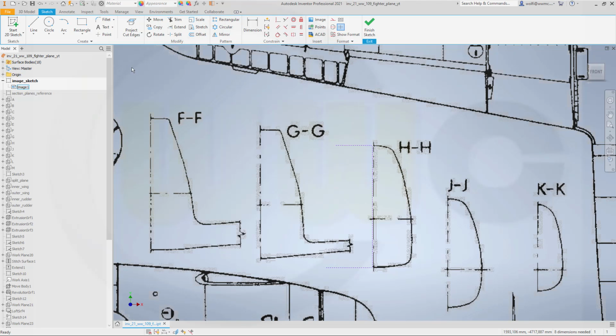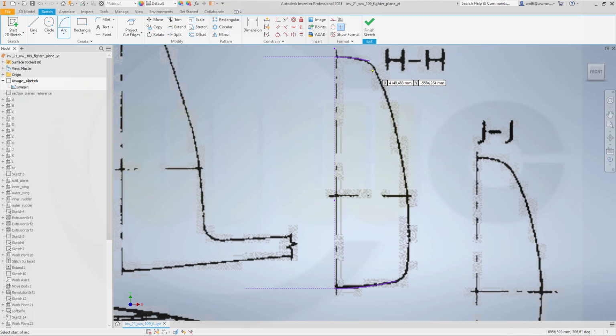And then I want to go for arcs, and I think I have tangent arcs. Yes, I want to use a tangent arc here, go in there, and another tangent arc from this endpoint in that direction. Then I want to use a 3-point arc. Zoom in a little bit, from this point to that point and that midpoint here.